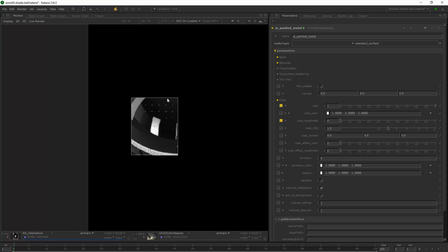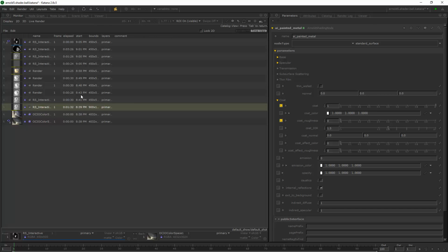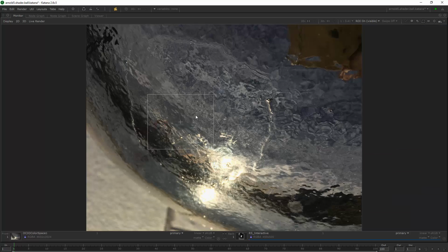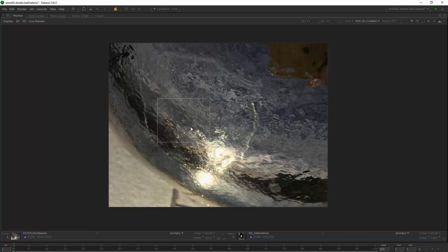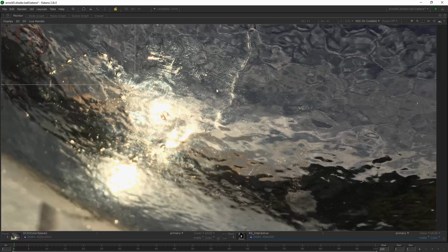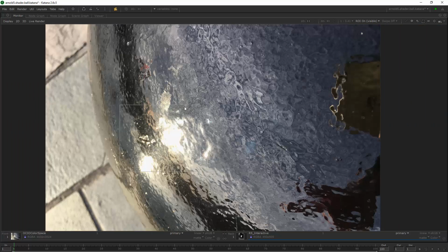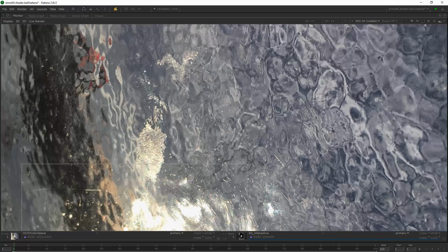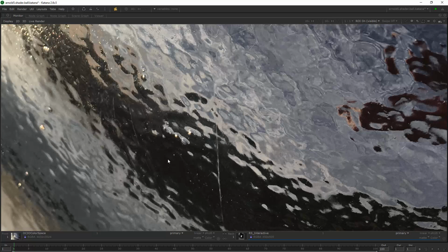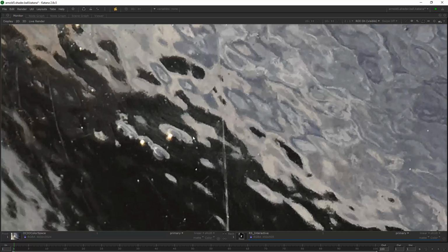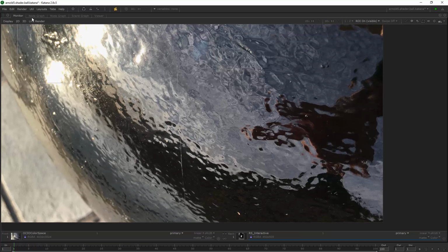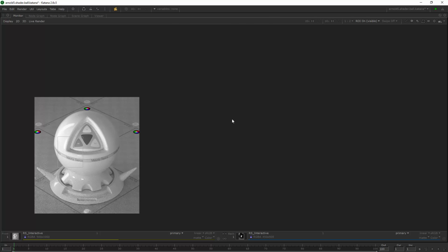So this is now with no roughness, and you can see in the reference images actually that there is some roughness to it. You can see that the glints bloom out a bit, and in the other one, you can see that there are, I don't know, fingerprints or some splotches. So I will just introduce a subtle amount of roughness, and you can actually see the reflections are not 100% crisp. There is something going on there, right? So keep that in mind as well.